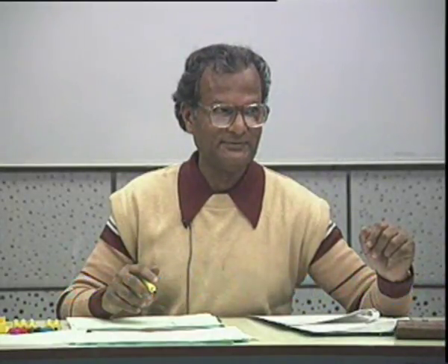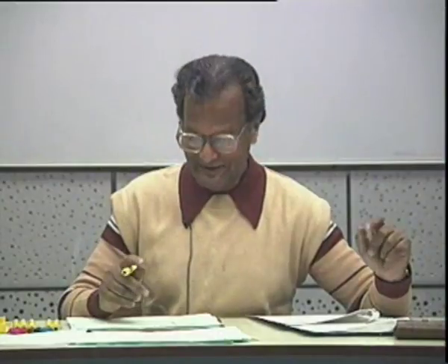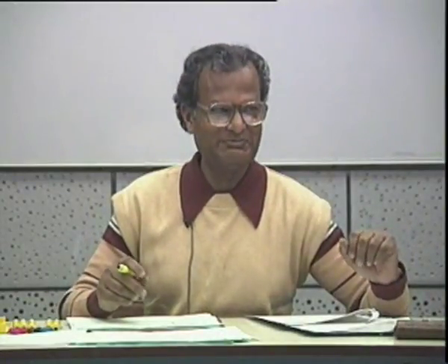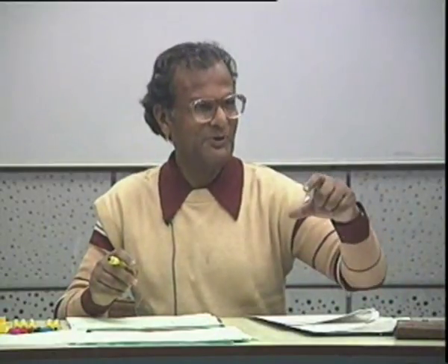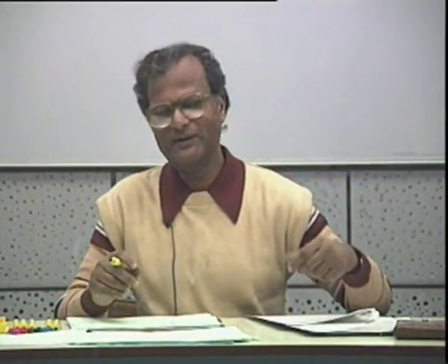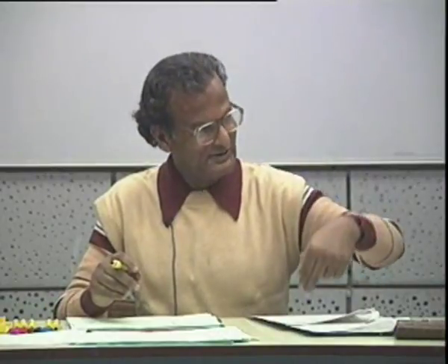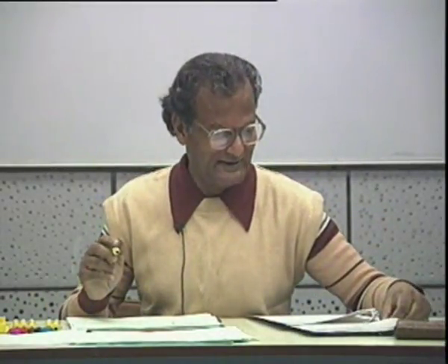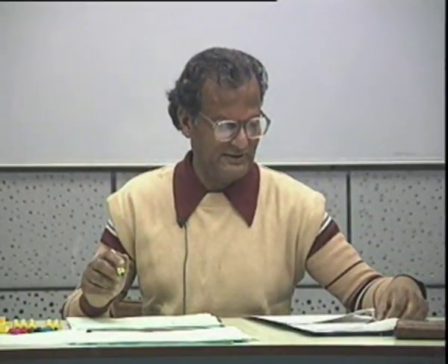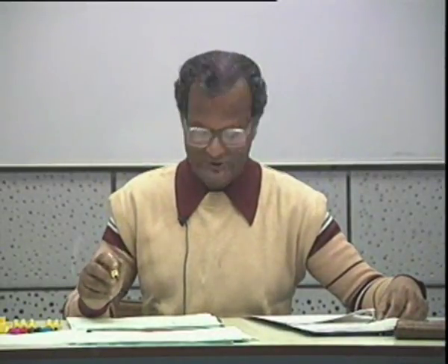And would we be able to see that when we bring V in down? Well, you see what happens. It has to come through the active region. So from 0.8 it cannot suddenly go to 0.5, or 0.2, it must go through 0.7. Okay. Now, so the intermediate state is active. V in must be reduced until Q1 is active.